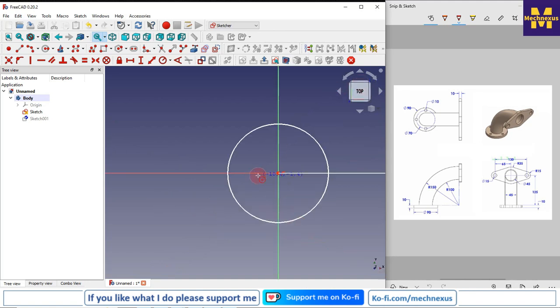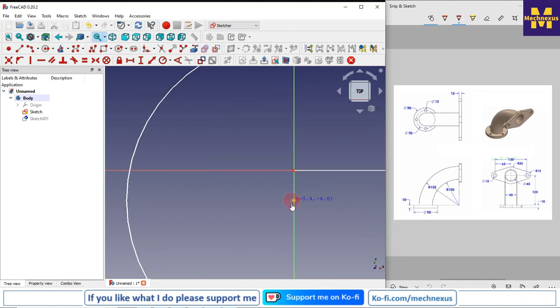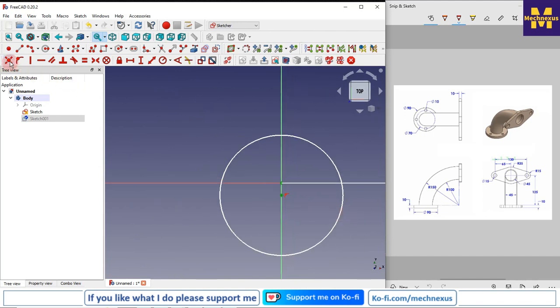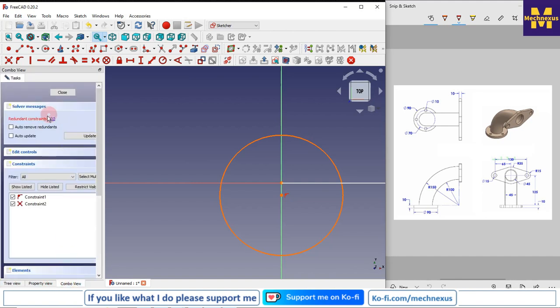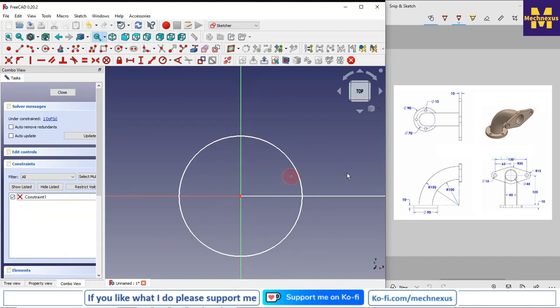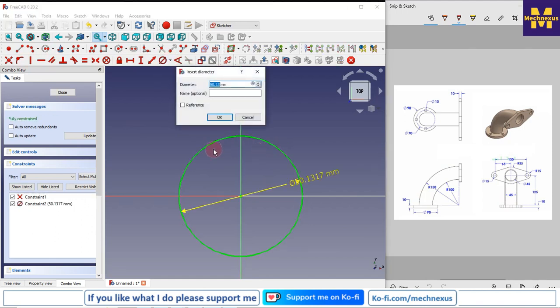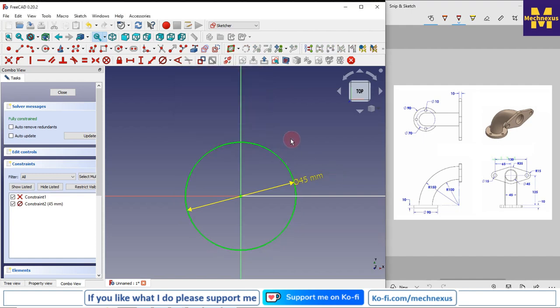Now I will switch to the top view, and it is not constrained, so I will select this point and my origin point, and I will say merge. So here is a conflict, so I will delete this coincident constraint. Okay, so our pipe diameter is 45, so I will select my circle, and I will give the diameter 45,